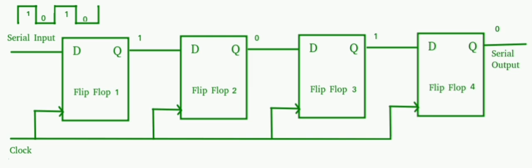Flash type ADC. For n-bit conversion, a flash type ADC requires 2^n − 1 comparators, 2^n resistors, and a 2^n by n priority encoder. It is the fastest ADC among all. It is also known as the parallel comparator type ADC.